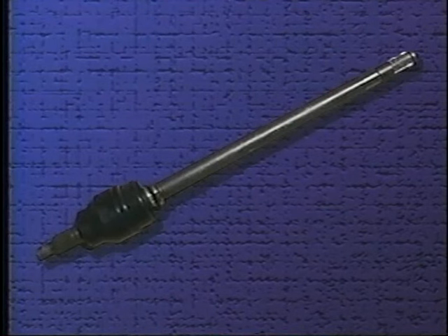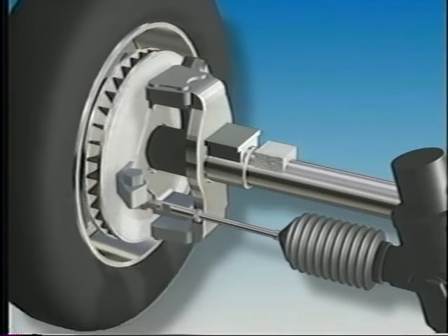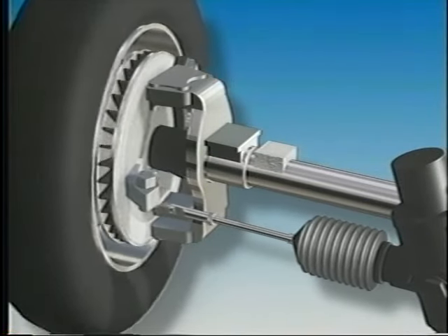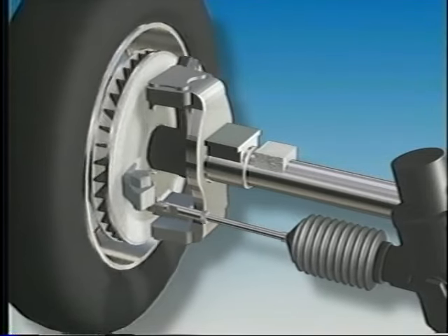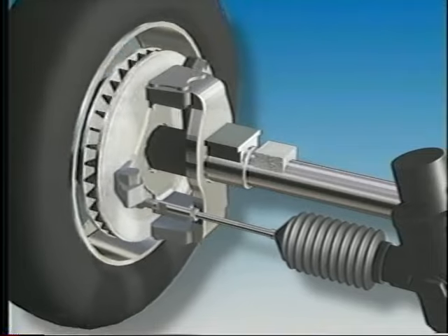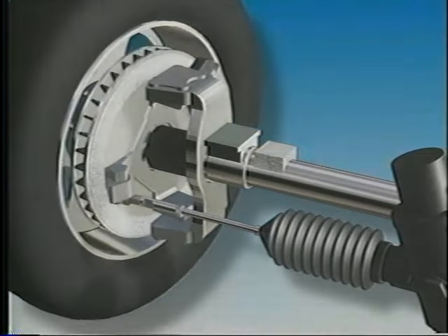Quarter shaft operation parallels what we've seen on other axle shafts that are a constant velocity or CV joint. The rear axle quarter shaft knuckle joints are able to move independent of one another. This allows for individual quarter shaft movement, though due to mechanical constraint, only normal axle rotation and steer of the wheels at the CV joint is allowed. On a practical level, there is no camber or caster adjustment. The only adjustment is for toe.